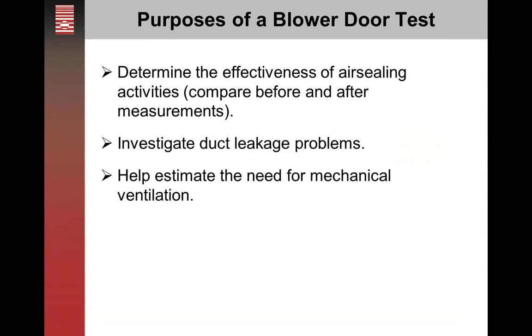We also want to determine the effectiveness of air sealing activities. What was the number before and what was the number after? Did we actually fix what we thought we were supposed to fix? It's also used to help investigate for duct leakage problems and also help to estimate the need for mechanical ventilation.